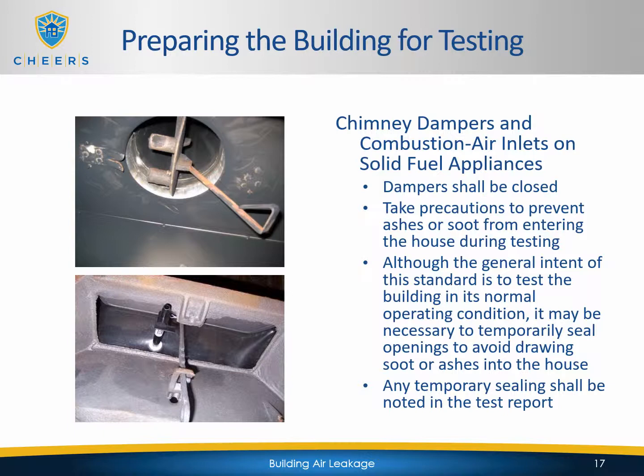So you will be depressurizing the house, meaning that you'll be sucking air outside of the house. When the blower door starts and you depressurize the house, the blower door is going to be sucking air from whatever crevice it finds within the house itself. If there are ashes or dirt or anything in the chimneys, in the appliances, or whatever they may be, those ashes, that dirt, those contaminants will be pulled into the house and through the house, depositing on the carpet, making a mess, generally speaking, just causing problems. So that's why they allow you to do this if need be. Any temporary sealing, keep in mind though, shall be noted in the test report.